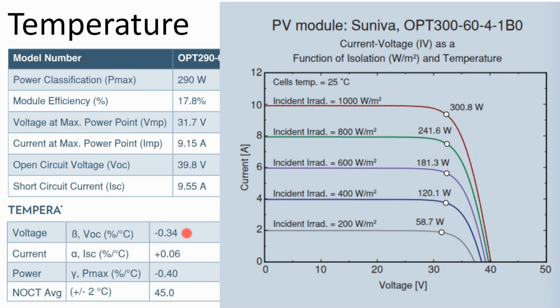The way you make sure you don't do that, there are rules in the National Electric Code about overvoltage and overcurrent. The manufacturers have taken these rules and put them into sizing software, so use manufacturer sizing tools. We'll get into that in the program. But the point is, the rated current, the rated amperage, are different than the design current and design amperage. You have to allow for more allowances than that.